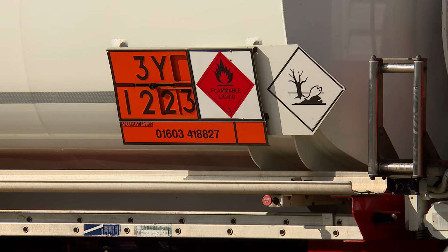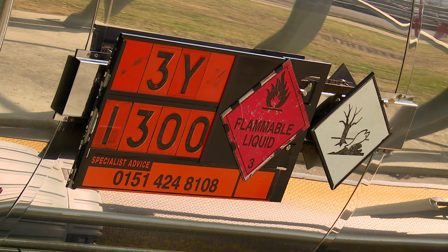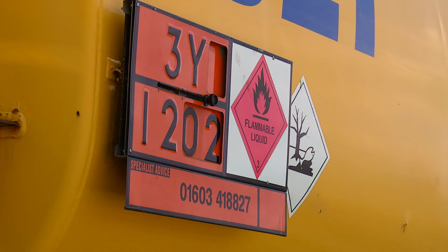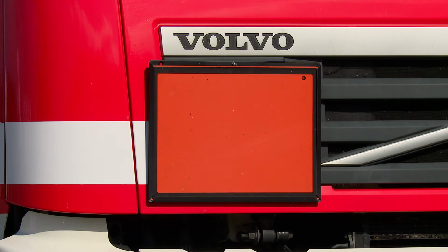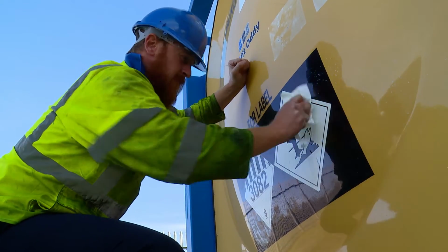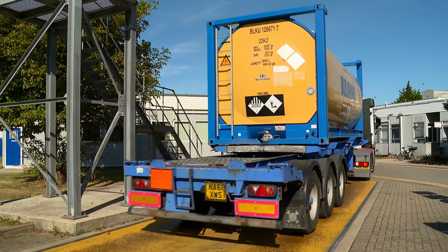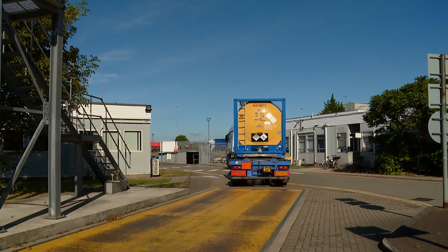Signs indicating the hazards associated with the loaded product are placed on the vehicle. These must be applicable for the duration of the journey to the countries involved. In the UK, these include hazard boards with the emergency action code, UN number, emergency telephone number, and hazard class pictograms. Mandatory orange squares are added to the front of the vehicle. International journeys under ADR regulation are placarded with diamonds on each side of the vehicle with front and rear hazard identification number and UN number.